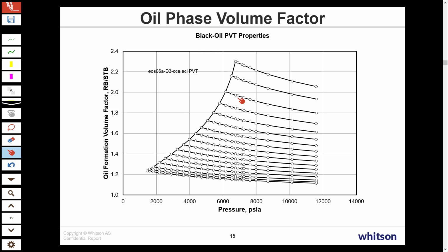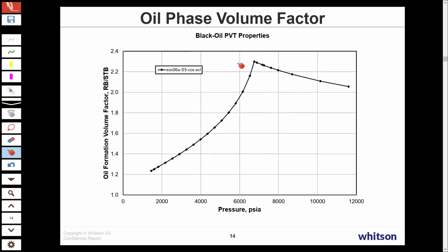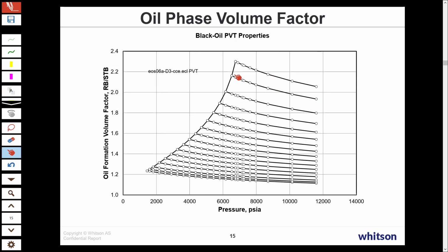Now, this is an example showing both the saturated, the previous curve is the saturated formation volume factor behavior, and the undersaturated. But actually, every oil, as this oil loses some gas and goes down to this oil will have its own undersaturated set of properties. You see, it'll be a little bit less steep, the change in the oil volume. The compressibility is decreasing when you lose gas,